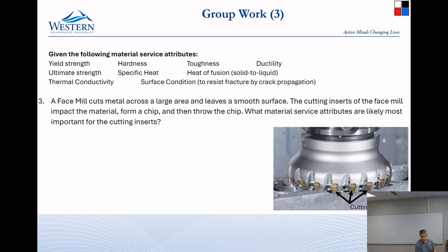We also said surface conditions, so if any of the cutting inserts have a little tiny crack, then it could just fail immediately. Okay, yeah, so the little tiny cracks will cause them to fail.